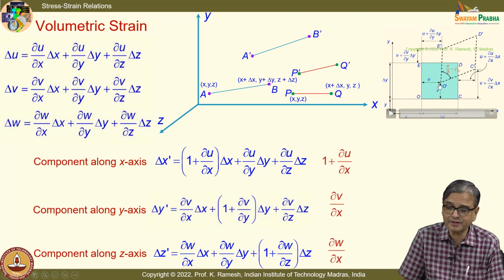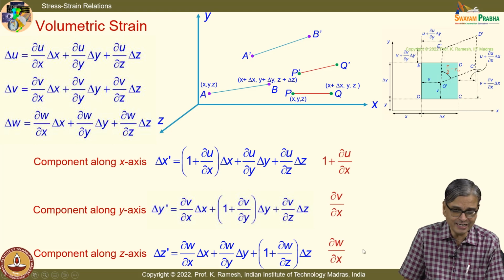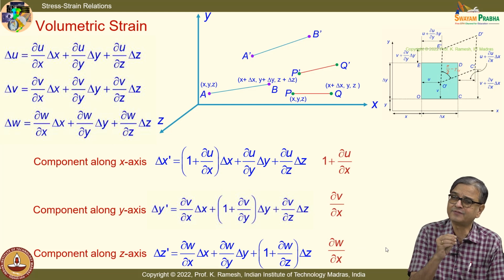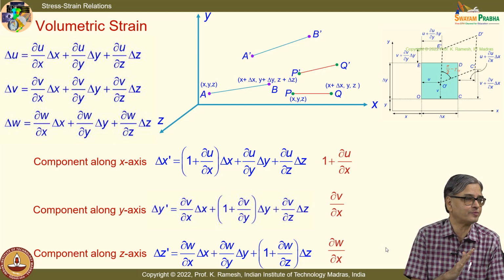See, here we have taken the 2-dimensional situation. Okay, it has got distorted like this, and when you look at what happens to this, it is u plus dou u by dou x delta x. That is what you are putting here. Fine. And then here you have shifted by dou v by dou x. We have missed out what happens in the z direction. So, the extra quantity dou w by dou x comes. Leaving that, it is very similar to what we have done for a planar situation. Now, we have graduated to a 3-dimensional situation.